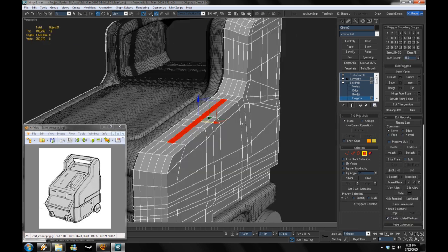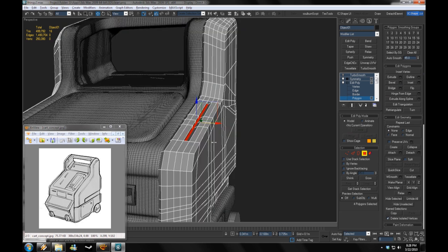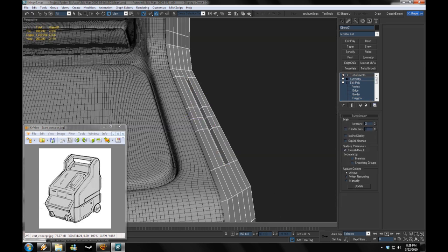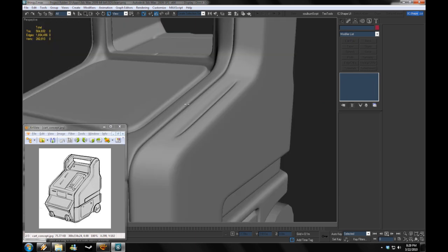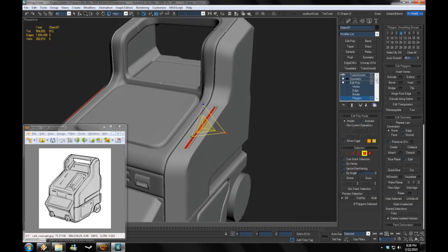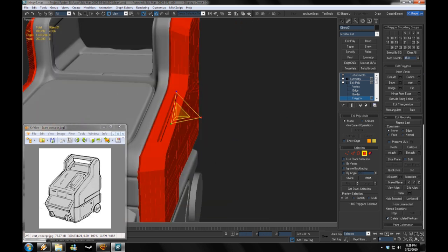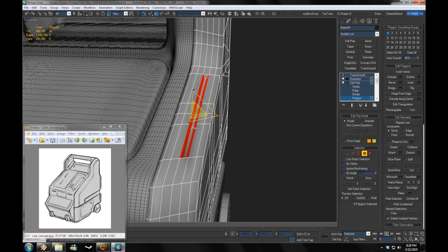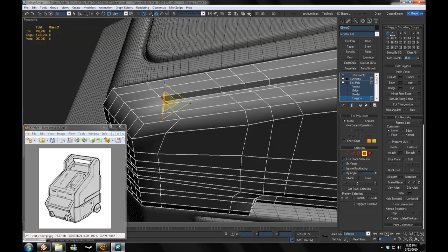And I'm just going to make this a little bit more dense and add in this little light strip. This is just going to be normaled in on the low poly. Like I said, it's very important to think about your low poly when you're making your high poly. And that's not looking good as it is. It's indented, but it's not perfect. So I'm going to add in some edge loops. I'm trying double smooth, but I'm not a big fan of it right now.